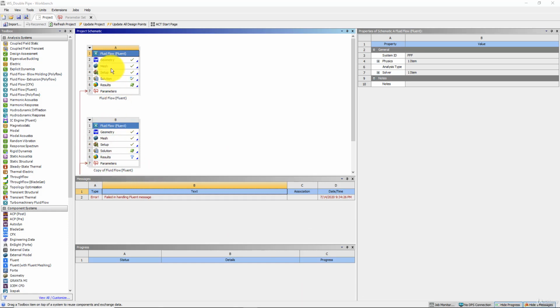And in this way you can rename: right click here and rename. You can say this is the coarse mesh, and then the second case is the medium mesh, and just change the mesh from cell number 3 B3 and also here A3, and also create another duplicate copy of this setup, and then just change the mesh and go to Solution, and from here update, run for 500 iterations, and you will see the difference in the results with the mesh changes.